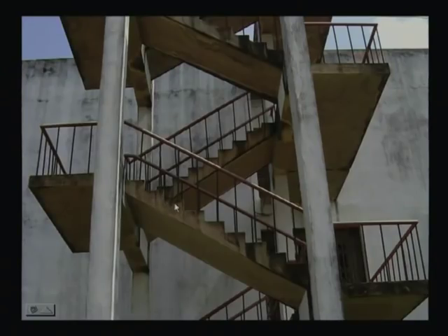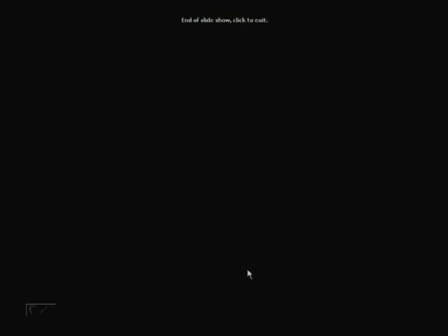What I can say here is that there is one step here, you can see those steps, all the steps. So you have to consider the dead load of the steps also, the weight of the steps, and this is what is called the waist slab. How to design this one? I shall not consider the first case, where the steps were one after another. Here we are assuming these steps are supported by this slab. That means I can design that slab.